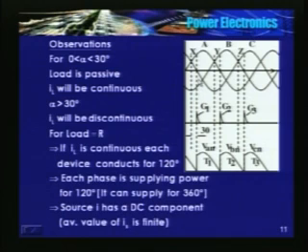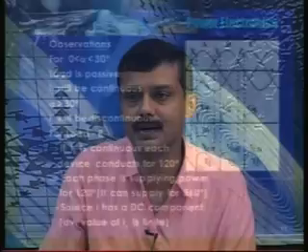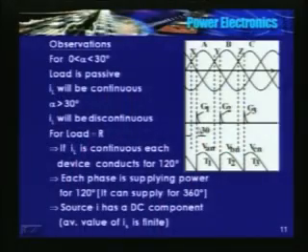Instantaneously the output voltage jumps to the value proportional to VAN. So this is the value VAN. It will jump to VAN and continue in this fashion for 120 degrees, provided the current is continuous. So T1 conducts from this instant till you trigger T2. At this instant T2 is triggered, the instantaneous value of VAN becomes 0, that is why it touches the x-axis.